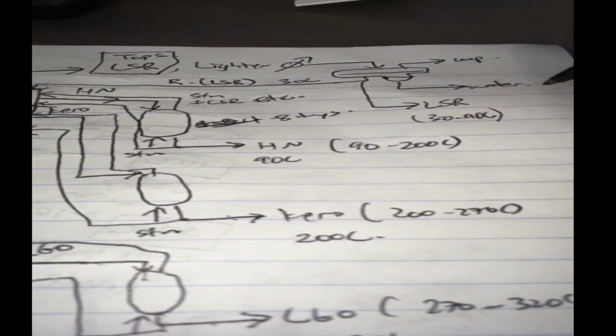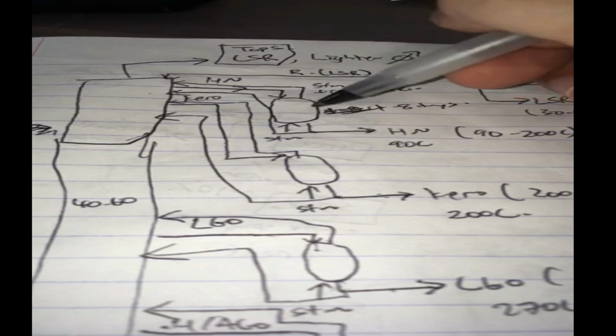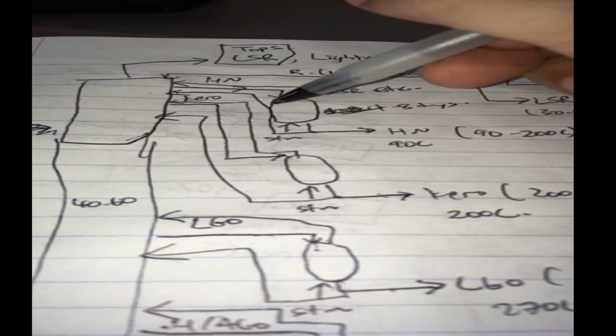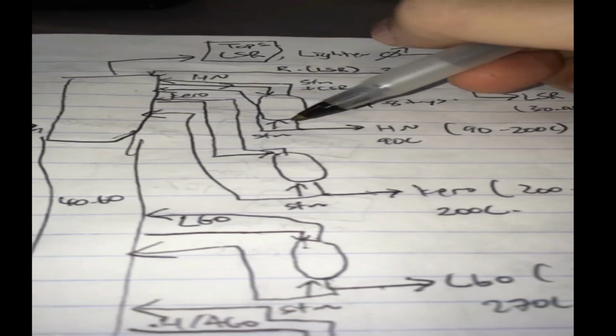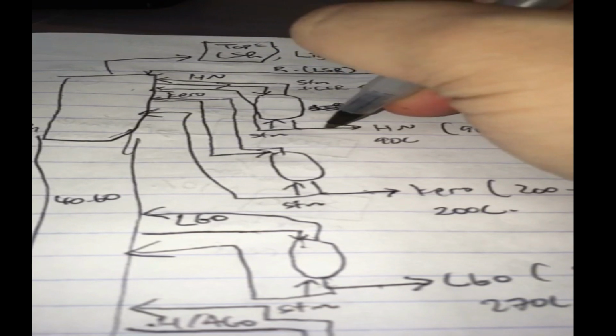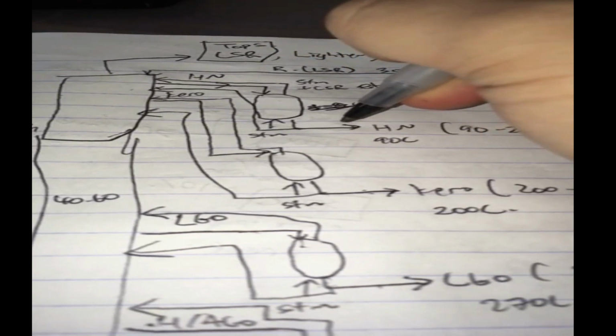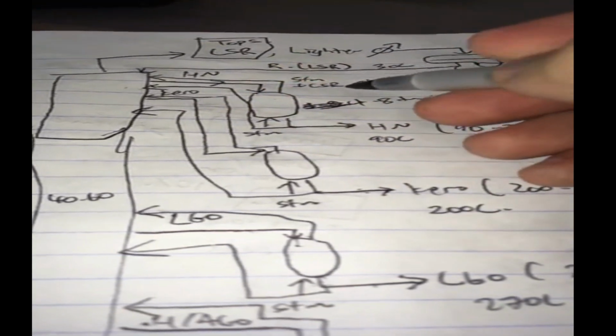Light straight run, you can send back to the tower as reflux. Water, you collect it out. And next, you have side strippers for heavy naphtha. You draw a heavy naphtha fraction. Side strips, about 4 to 8 trays. You have steam going in. And the heavy naphtha will come out hot. It will heat up the crude. And you can send some of it back as reflux.